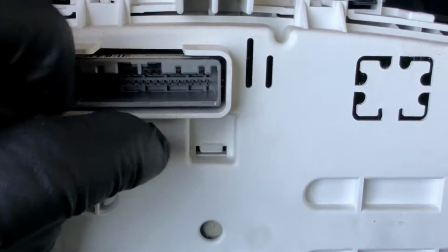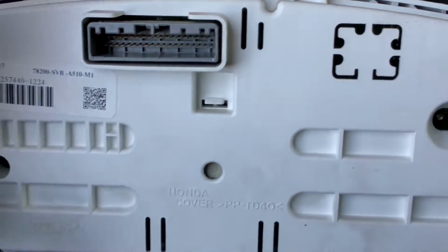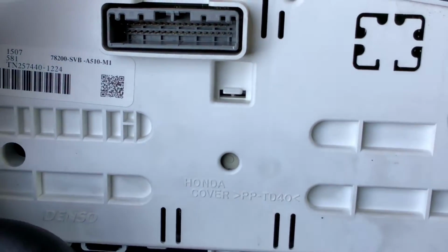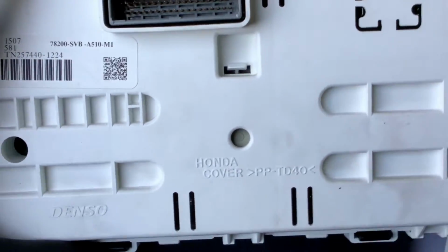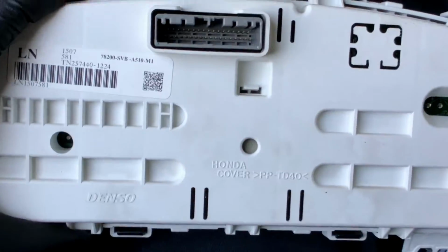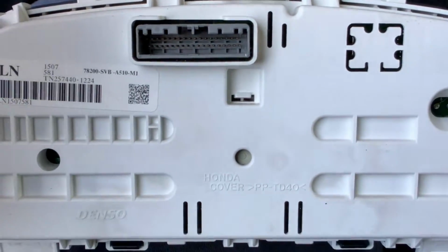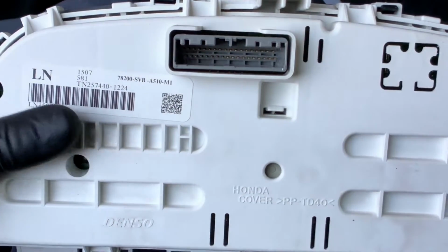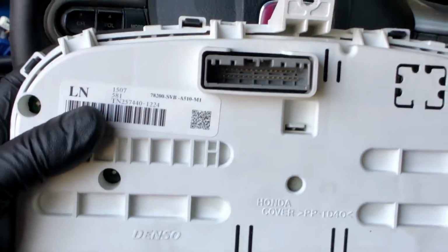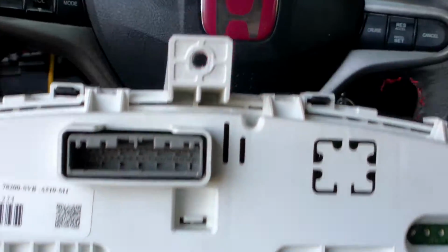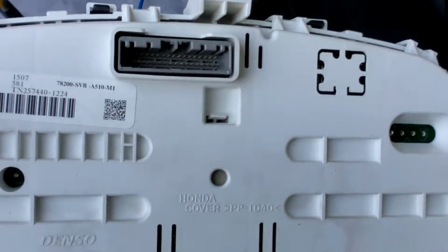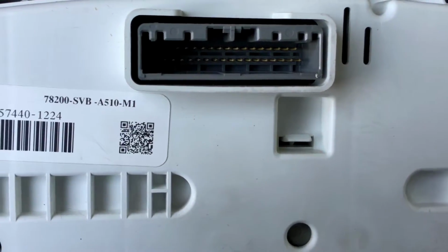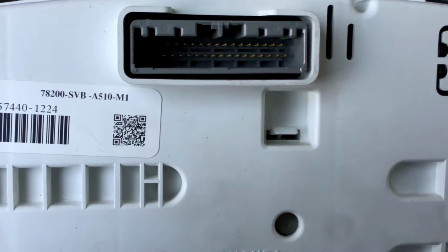I'm actually gonna take this, and I'm gonna go across pin number 1 and 19, and measure the resistance of this. If it's close to 124 ohms, then I'm gonna leave this alone, and I'm gonna call it a video, and I'm gonna wait for some responses so that I can get some help with this. And honestly, I should be getting into more communication stuff. Let me go across that, check the resistance, and then we'll see what kind of stuff we got.